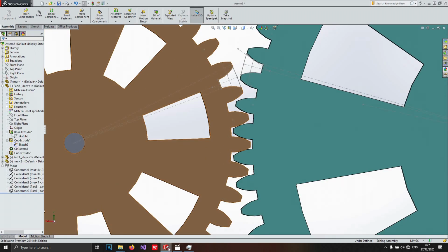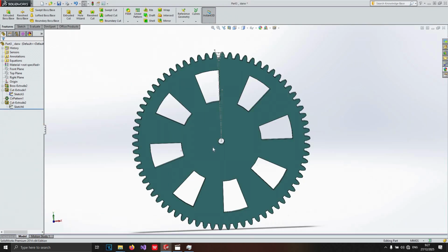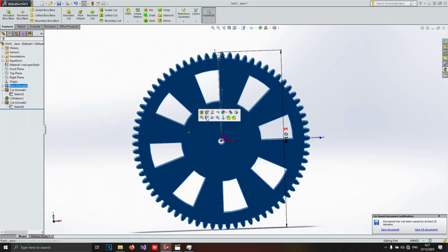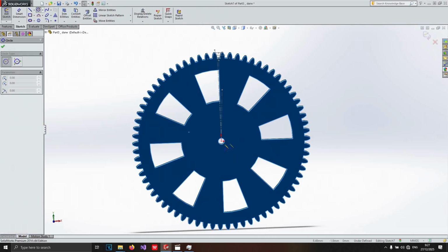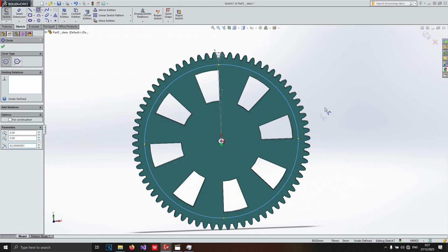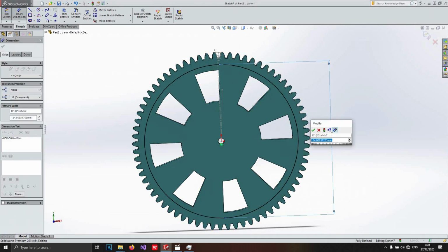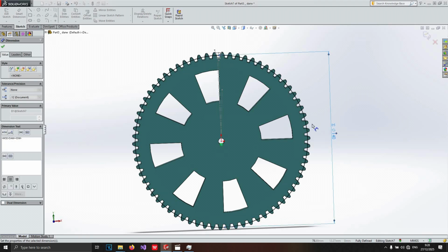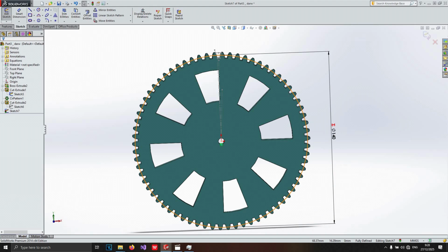To simplify the assembly process, especially when creating gear motion animations, reopen the 40-tooth gear and 70-tooth gear part files individually. Add construction lines on the pitch diameter, PD, of each gear. These construction lines serve as additional references to make mating the two gears easier, more accurate, and more stable.